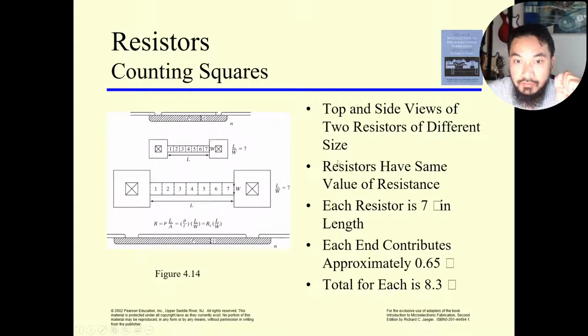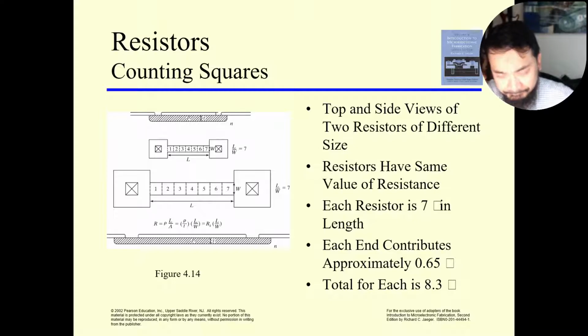Now, if you look at IC design, for metallization, the tracks connecting different parts of the circuits have a standard size and dimension. This is done to control the total resistance of the whole circuit. You want to know the resistance of the whole circuit, because at high frequency and very low current, these values will determine the performance of your device.